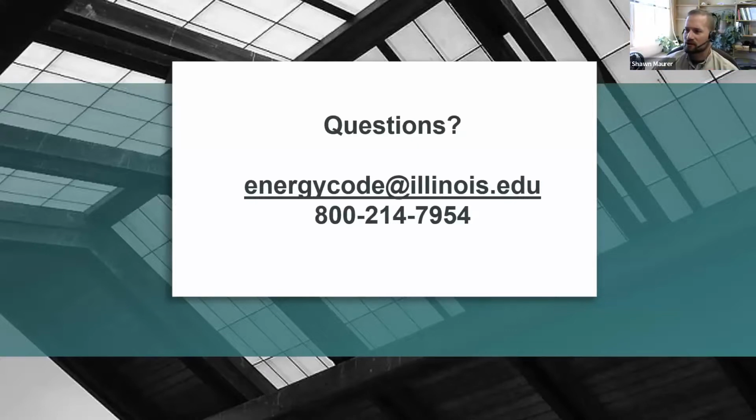Question here: are the heating and cooling improvements based on the ComCheck report? So the ComCheck report is based on the 2021 IECC requirements. ComCheck has been updated. It does have the 2021 IECC requirements in it now. So as you're selecting the different efficiency options, it will account for those in your ComCheck, percent beyond code requirements. Those get calculated in. So yes, that would be included in there.